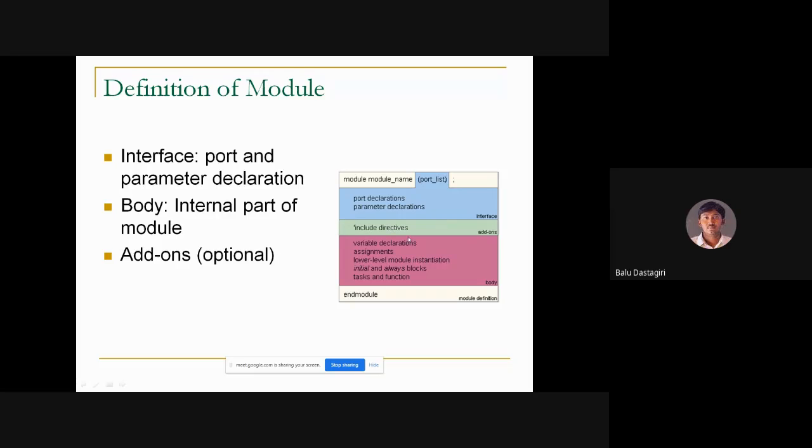These are optional. After that, depending upon the type of modeling, the internal body structure will vary. After endmodule, everything should be in lowercase letters. If you use uppercase, you will get an error during simulation.